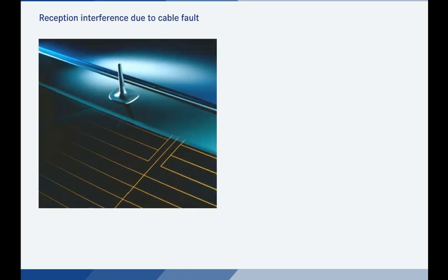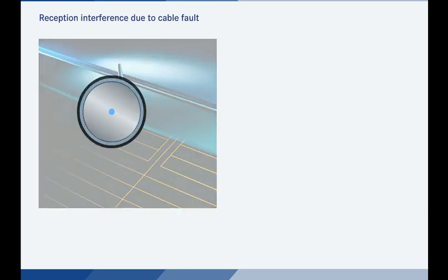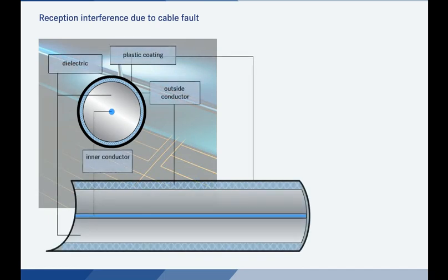Radio reception can also be affected by interference inside vehicles. The outer mesh metal shielding of high-frequency cables, in particular, must remain at a precisely fixed distance from the inner conductor, so that the high-frequency signal can be transmitted with as little loss as possible.